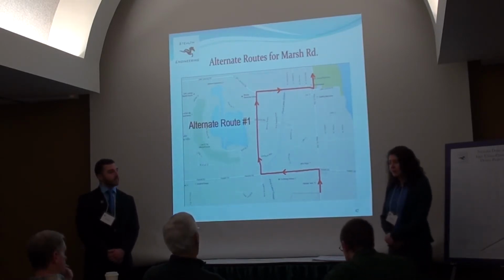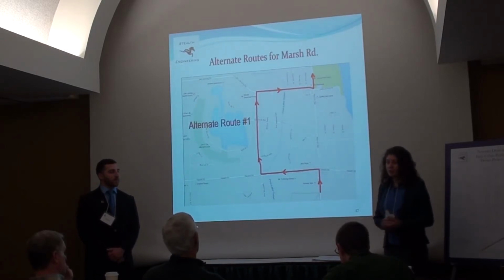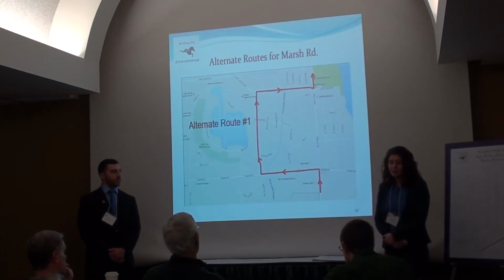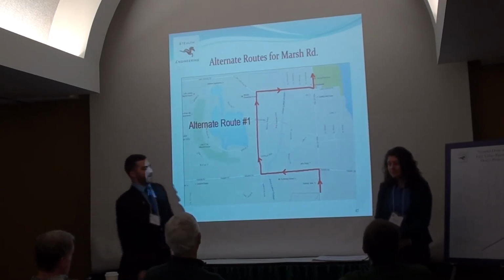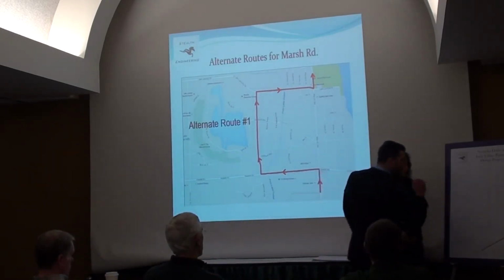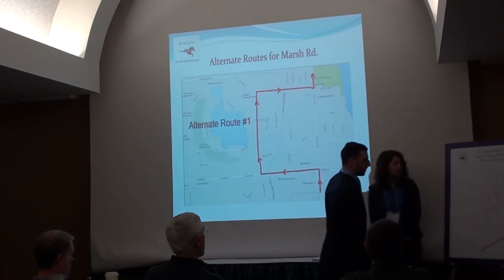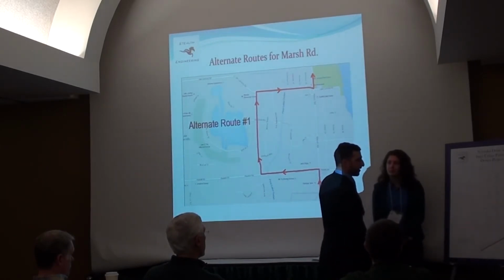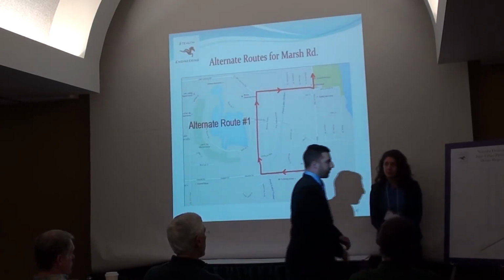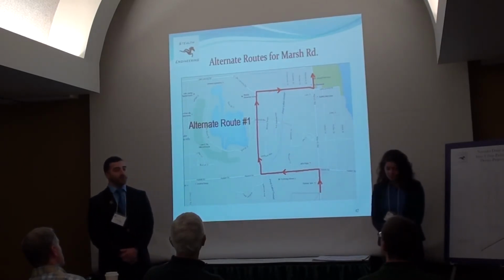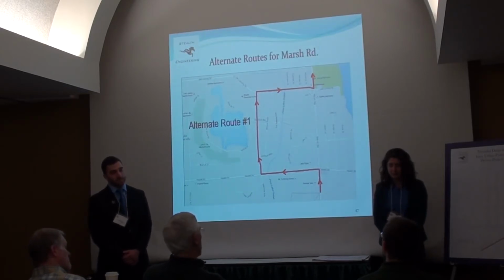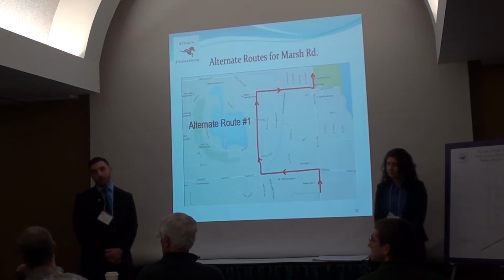As far as the swales as well, some of the houses were very close to the road, so these swales would be very close to their property. And that's one of the other considerations we took with the swales in our design. And with sidewalk, there were a few areas where sidewalk couldn't be implemented because it was getting dangerously close to that right of way. So as long as they don't fall within the property lines of homeowners, that's where sidewalks will be.